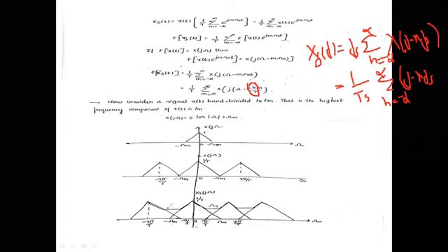Understood, my students? So, when I take the original signal with fs equal to 2fm, we can recover it by using the ideal low pass filter. And the spectra overlap when fs is less than 2fm. So we already saw this, the impulse sampling technique. But practically it is not possible to use the impulse technique. Impulse sampling is also called ideal sampling, or instantaneous sampling. So there are three names: impulse sampling, ideal sampling, and instantaneous sampling.